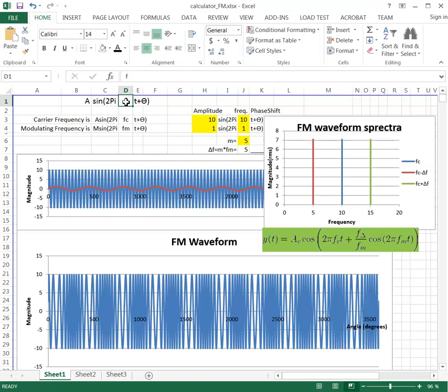Unlike an AM waveform, if we had some amplitude changes through noise or whatever, we can get some form of error. In an FM waveform, that simply doesn't happen because there's no encoding on the magnitude of the waveform. All the encoding is done in here with a change of frequency. Now, this is kind of quite cool.